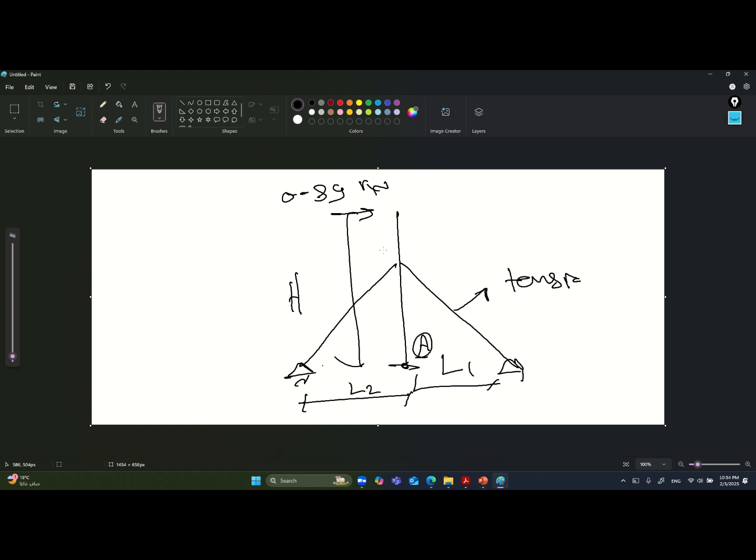He asks what is the maximum tension force that the support can carry. Of course, I didn't consider the reverse direction, so anyone will take the equilibrium about moment A. It will be something like 0.89 multiplied by h divided by L2. You will get this vertical force. However, the maximum force isn't here. When it is reversed, then it is in the opposite direction.